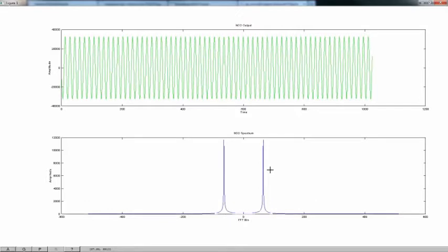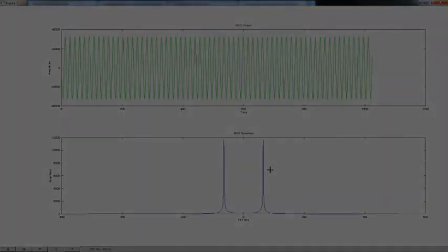So that's how you can integrate Octave with Altera's SignalTap tool. And so that's a basic NCO core, and that's pretty neat. And we can use that to connect to the real world and use a DAC and generate signaling that way. But what are some other techniques that we can apply to the NCO to make it more meaningful to real world applications?